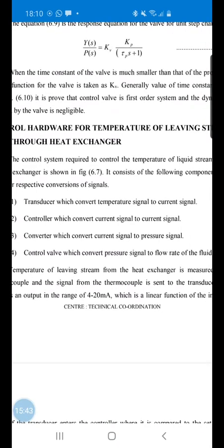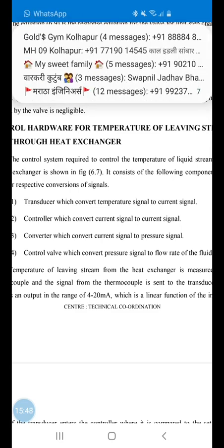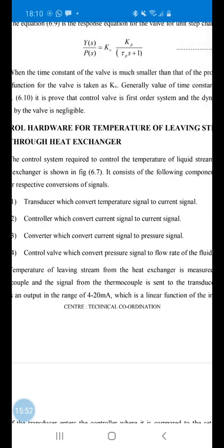So this is how you can study the pneumatic control valve, which is of two types, air to open and air to close. All these control valves work between 3 to 15 psig. Sometimes the question arises, why not 2 psig or why not 16 psig? So my dear students, if the pressure is reduced below 3 psig, or increased beyond 15 psig, there is no change in the position of the diaphragm, stem and plug.